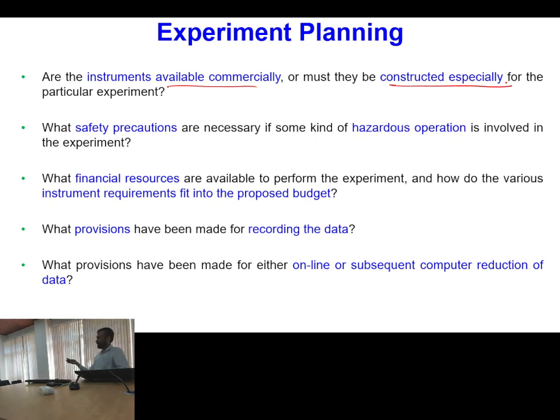But we know there is no standard instrument for heat transfer coefficient. For flow rate we have a standard instrument, so I need not design the system again; I can simply take a commercially available device. For measurement of temperature you need not design the thermocouple on your own. You can take a commercially available thermocouple and use that.